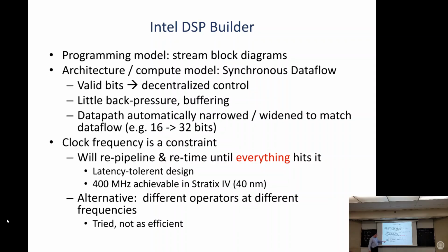In this case, there was an earlier version of this tool that actually did run the different operators at different frequencies. So it didn't do this trick of run everything at the same frequency and just widen it over the data path. And it didn't work as well. So this is another case where we actually have an apples to apples comparison where it was actually better to try to make everything run at the same frequency and just change the data path width.